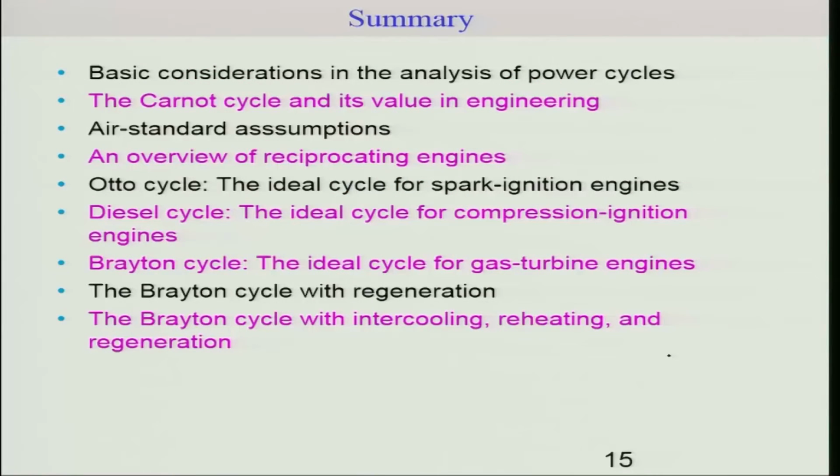This will be the end of the lecture. Let me just summarize what we have covered in this topic on gas power cycles. We have looked into the Carnot cycle, which acts like an ideal cycle. We have considered the air standard assumption in our analysis, and an overview of a reciprocating engine. We have considered the Otto cycle for spark ignition engines, and the diesel cycle for compression ignition engines. And today we looked into the Brayton cycle, which is an ideal cycle for gas turbine engines. We also considered regeneration, intercooling and reheating as a part of increasing the efficiency of the Brayton cycle.